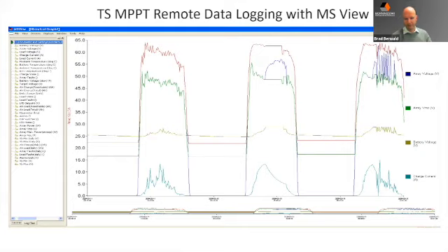If you look here, you can see pretty much in the middle, if you can make out the graph there, that's pretty much a perfect solar day. You've got a high VOC, you've got the VMP there, and in the blue and the green on the upper portion. You've got the battery getting a perfect charge in the yellow in the middle. And the blue line at the bottom inside the power curve is a perfect absorption, turning the current from 100% all the way down to float levels. And that's really what you want to see. If we saw that every day, I think our jobs would be a lot easier.